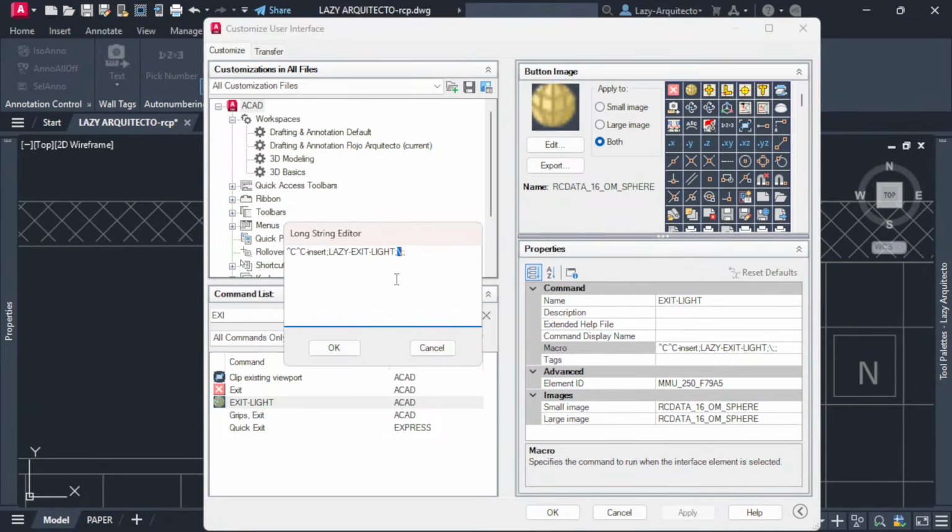That's to specify the insertion point, and after that AutoCAD asks for the scale. So I'm gonna simply paste a small piece of code that says getvar, meaning we're gonna get a variable value, in this case dimscale, and that's where we're gonna store the scale of our drawing based on our viewport.